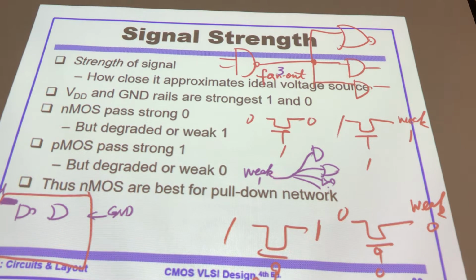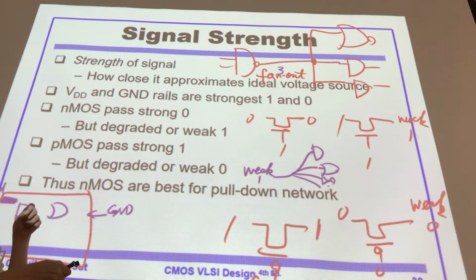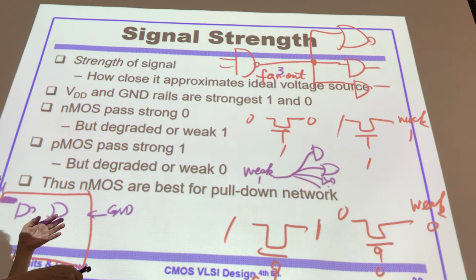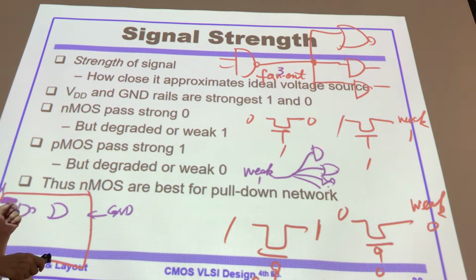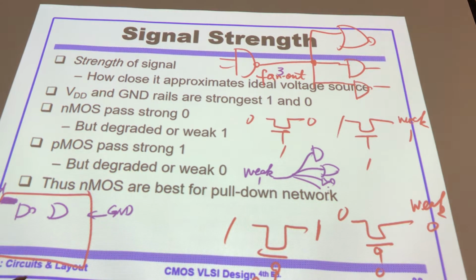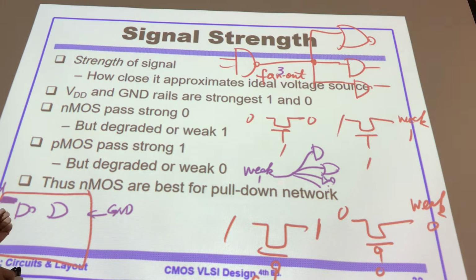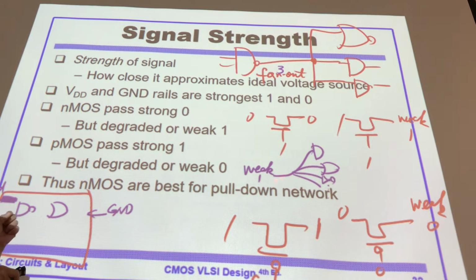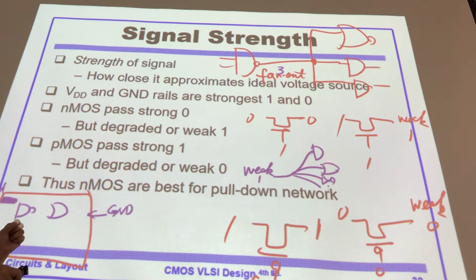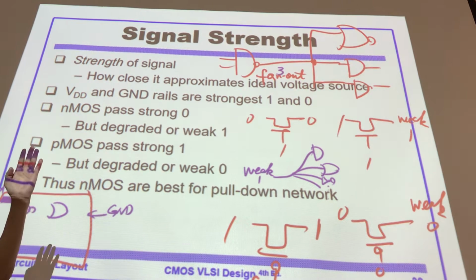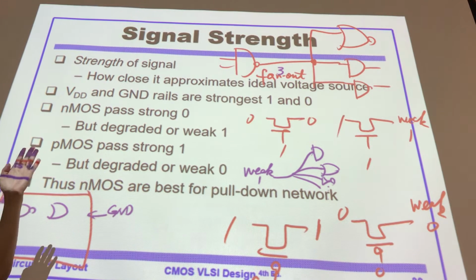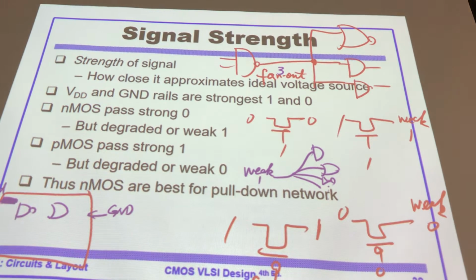For weak signal, we call that fan out. Fan out is not much, should be fine. But if the signal is weak, and we are driving a lot of fan out, like 20, 30, probably is not strong enough to drive so many gates correctly, because even in limited amount of time, you will not go up to enough high voltage such that it will give you signal 1. Is that clear?